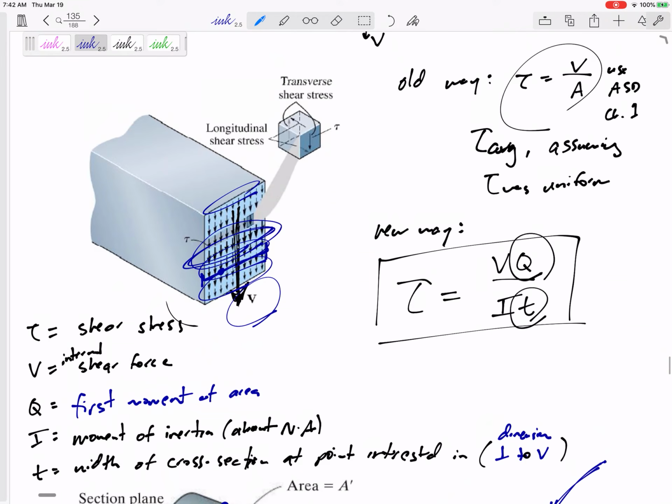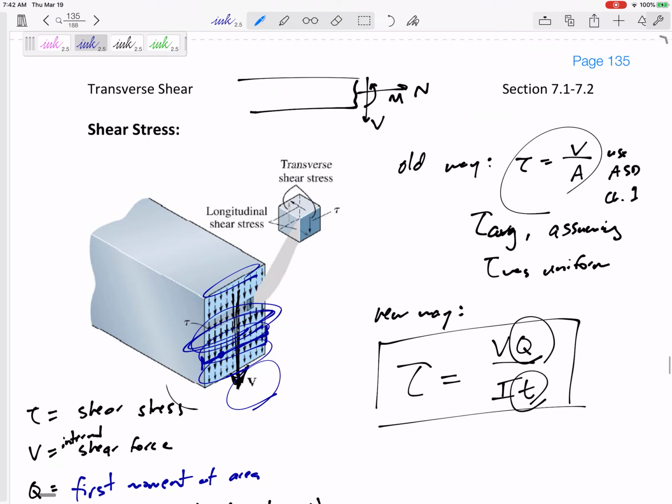All right, and one last thing. We've been looking at the stress on the cut, right? But if I was to look at a really small cube, an infinitesimally small cube, right here, the stress on the cut would be equal and opposite to the stress on the top of this cube if I was looking at a differential cube, just due to the sum of the forces.